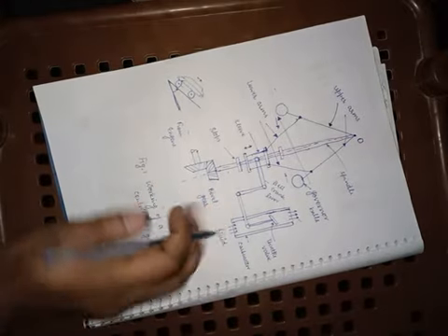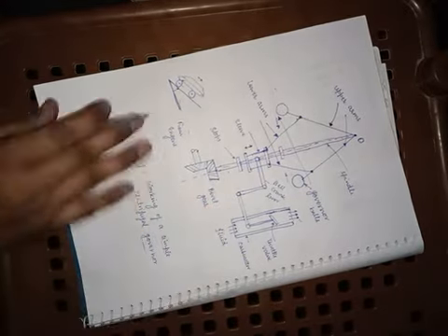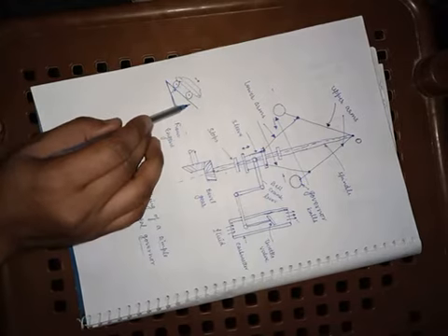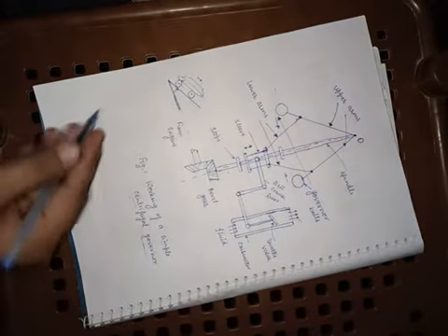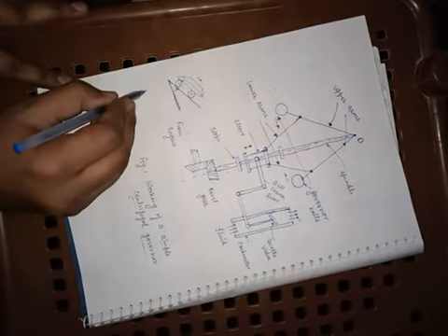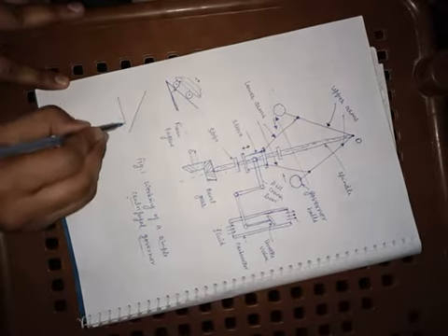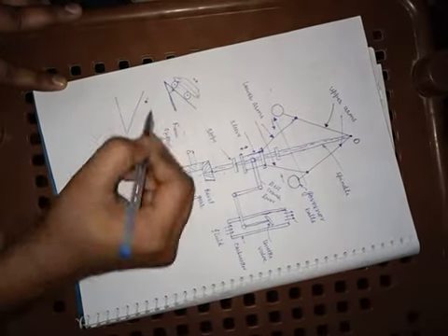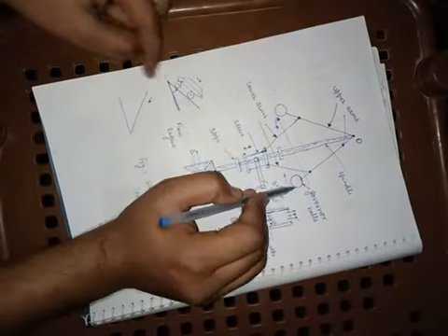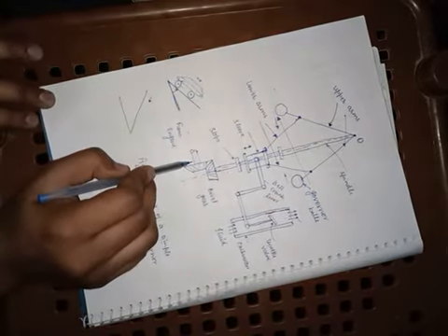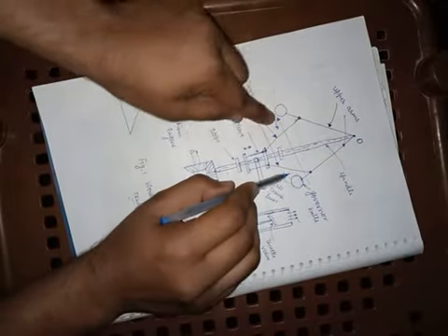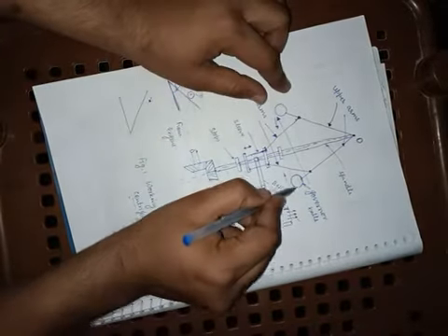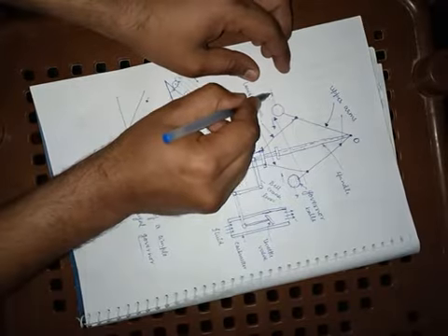In the second case, when you are moving in the downward direction, obviously your vehicle will move with higher speed. So whenever this vehicle is moving at higher speed, the engine shaft speed increases, and this spindle also rotates with more velocity. So these balls move very fast. Due to this, the centrifugal force increases, and this centrifugal effect will move these balls in the outward direction, far from this spindle. So the sleeve will try to move in the upward direction.